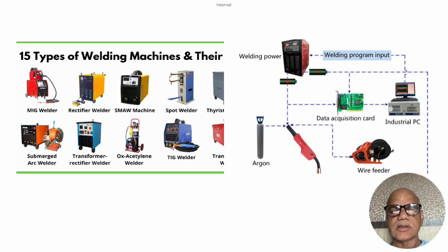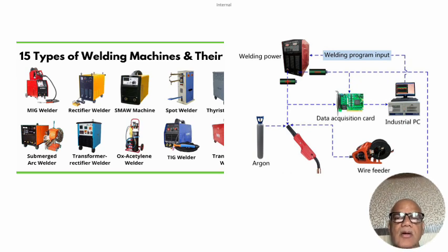When you increase current, wire feed also increases. So in such cases, you require different characteristics between voltage and current, and you try to use as flat voltage characteristics as possible, whereas in the electrode welding or the TIG welding, you try to use drooping, that is, voltage drops substantially as you change your arc length, and accordingly your current gets adjusted and current is maintained almost constant.